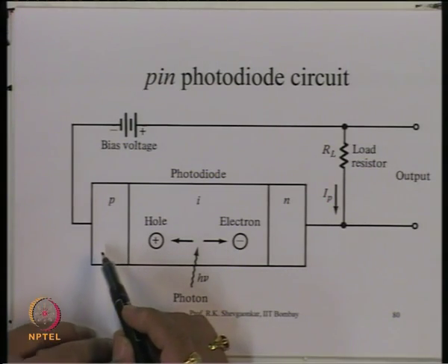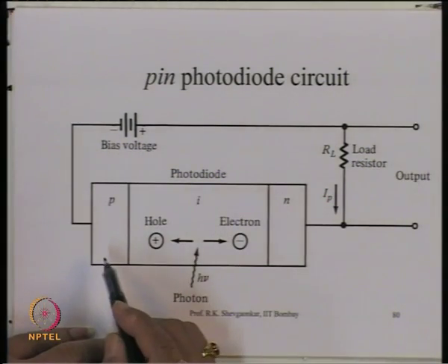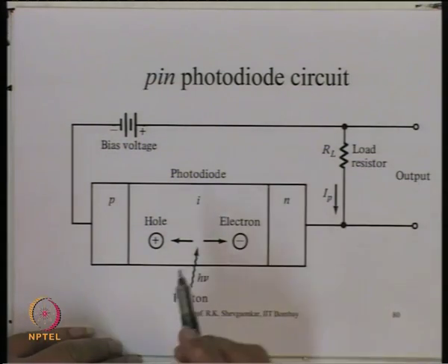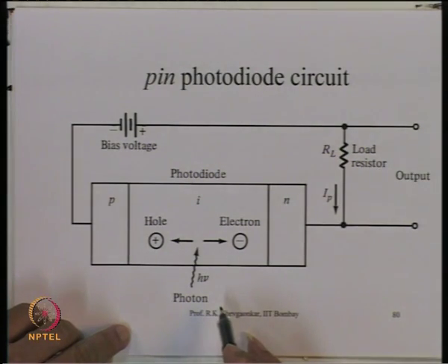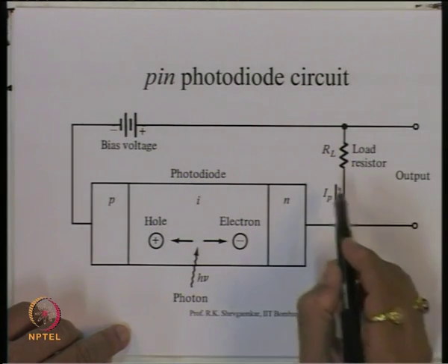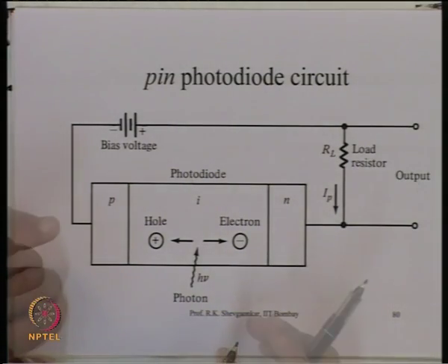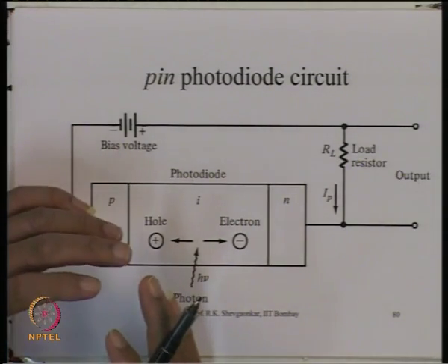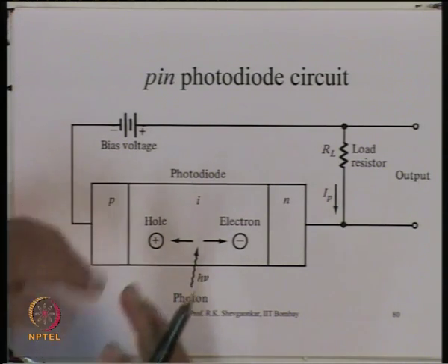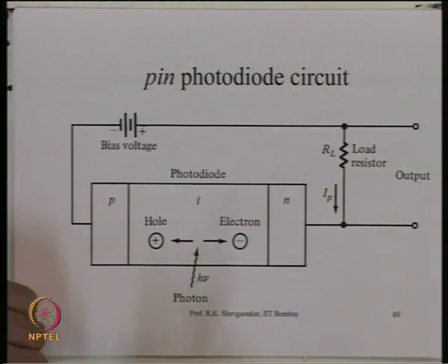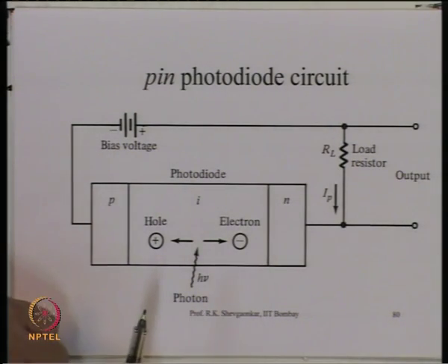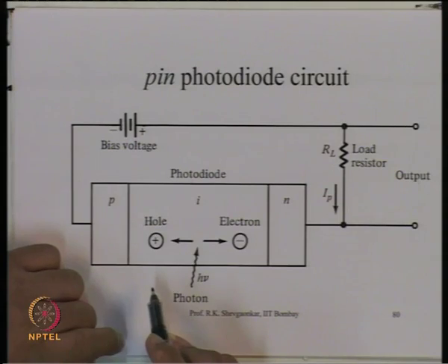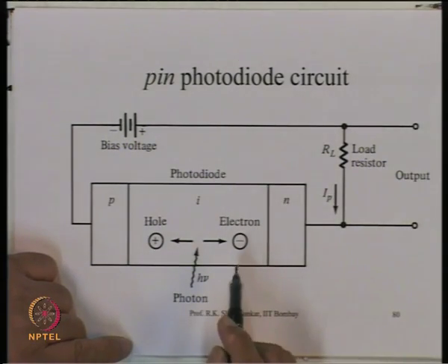Once we get that, this reverse bias junction has a current in the external circuitry, and the current flows through what is called a load resistance. So, you have a voltage developed across this resistance here. So, basically this conversion process of light to electrical signal is photon to current generation. That means this device essentially is a current operated device, or for a given photon flux we essentially have a constant current source here.